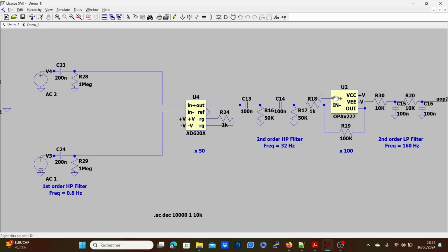And yeah, it's a little ugly here because I am using the SPICE models of the op-amps I actually use on my project. One of the reasons is whenever you're simulating something, you want to have the most reliable data, because there's no point using something that's just going to give you wrong values, especially in my case. For somebody who's broke like me who cannot afford an oscilloscope, I rely heavily on the ADC of my microcontrollers to observe the signals. And at the same time, I also need to rely a lot on the simulations to give me an idea. And it's also very, very important before buying a component to have a clear simulation.